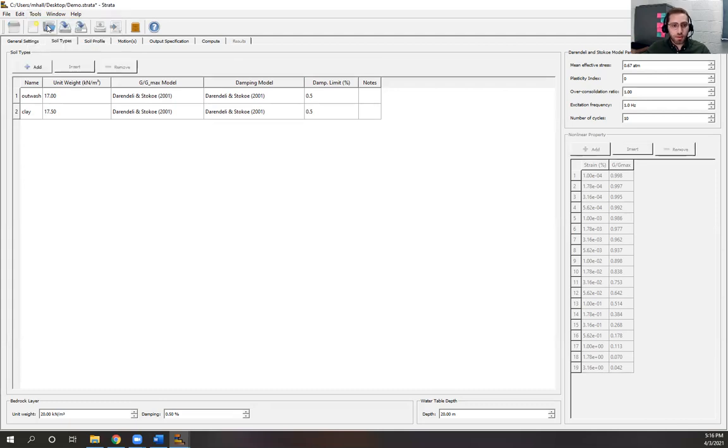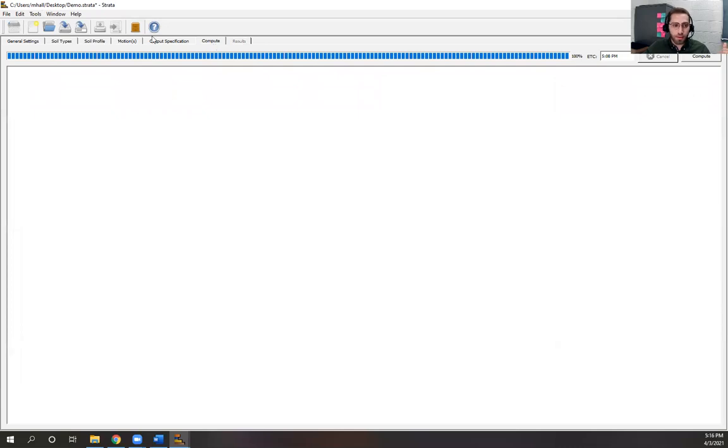So I'll click delete results, and now I can come over here, I can change the values. Previously, if Strata computed results and the results are plotted, you cannot change the inputs. And now, because I clicked delete results, you don't have results anymore. You have to compute again.